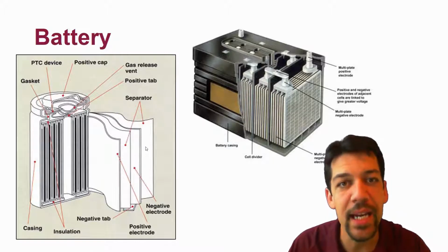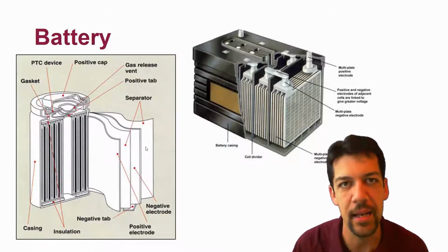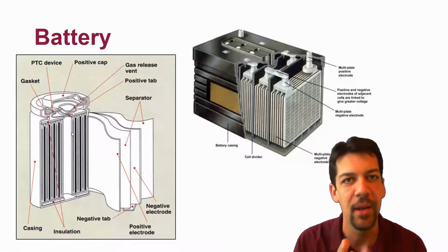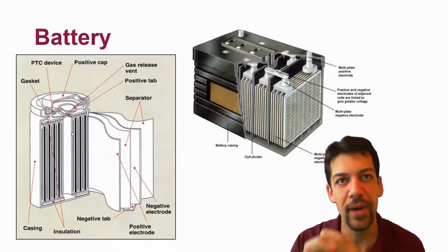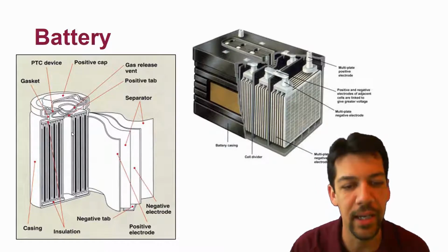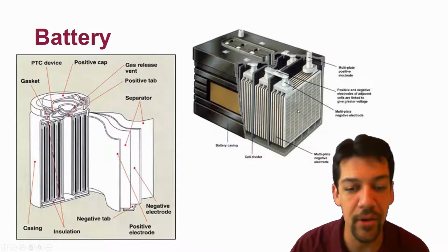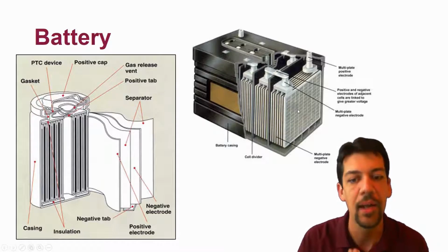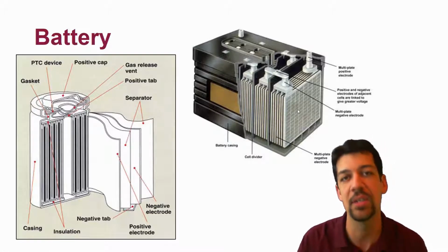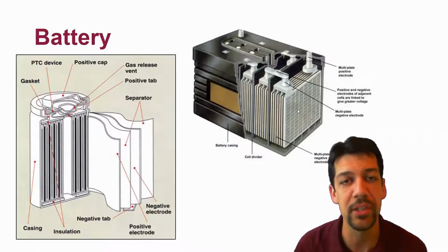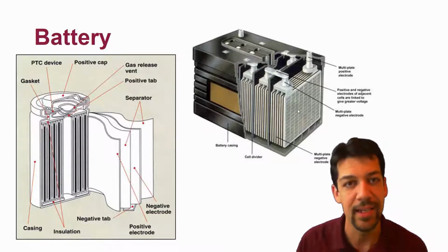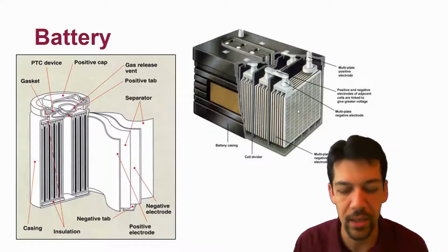And a battery is really a whole bunch of these little cells. A little one-cell battery is that same sort of illustration: two layers of that chemical separated by a separator and then rolled up into a little round. So that's one cell most of the time in a battery. Big batteries or other sized batteries are just conglomerates of those cells. They might be lined up in parallel for higher capacity at the same voltage, or they might be lined up in series for higher voltage for the same capacity, or some combination of the two to get bigger and bigger battery packs and to have those different characteristics that we need in our designs.